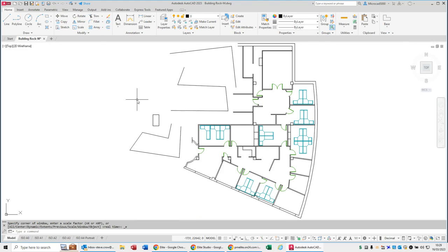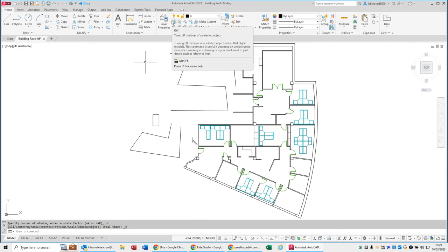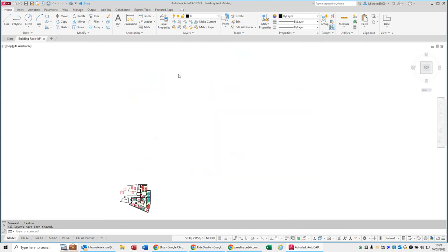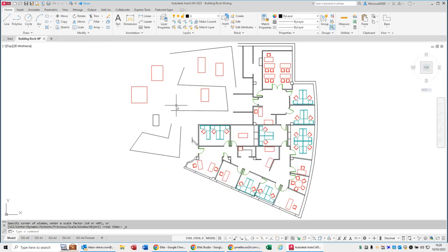I always recommend and advise people to stick with freeze/thaw. What you see is what you get. The number of times I've had drawings sent to me because the guy's double clicked his roller and the drawing disappeared into a dot in the corner, all because there's an object on a layer which was turned off. So when I get the drawing file, I double click my roller and I'll find it. Oh, there it is over there, 10 miles away. Delete it, double click my roller, bingo, the drawing's fixed. So that's the difference between on/off and freeze/thaw.